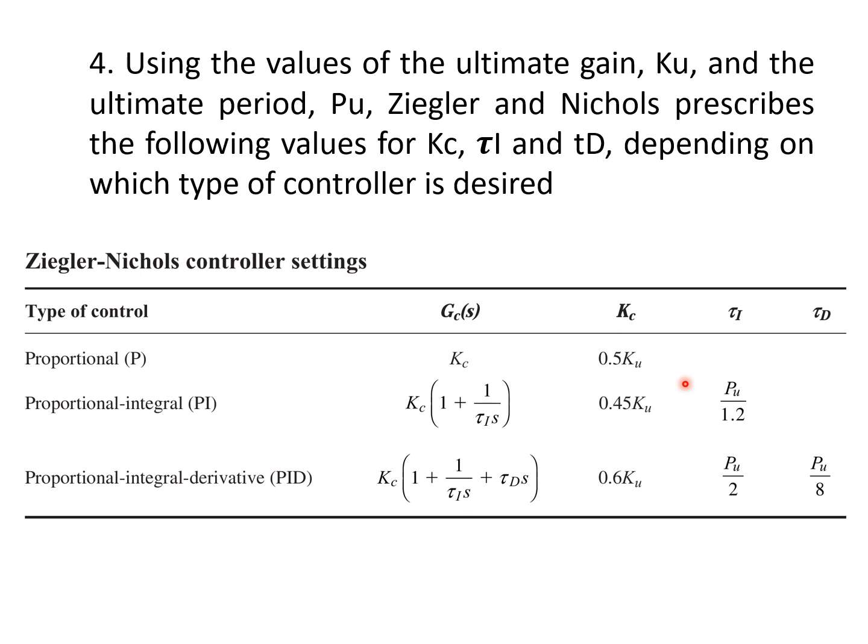It's a popular method. It may not be the best at the end, but this will give initial settings for your controller tuning. Later on, you can fine tune. So this is the advantage of having all these controller settings: they give you an initial value you can start off with for your controlling, not just at random from any point you want. As you can see in your lab, you may have used different values, but it still had some systematic way of changing your settings. That's fine, but that takes a lot of time. This one will give you an initial setting you can start off with, and then from there you can do your fine tuning to get a better controller.